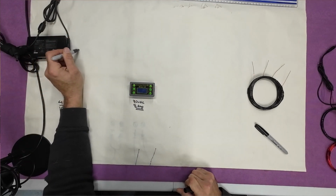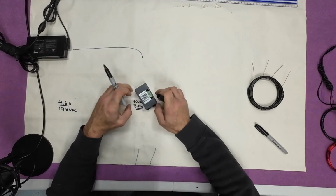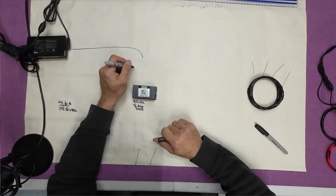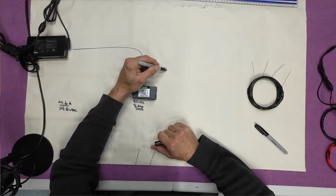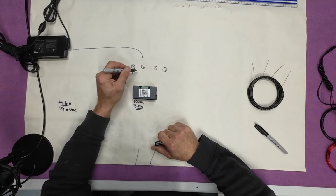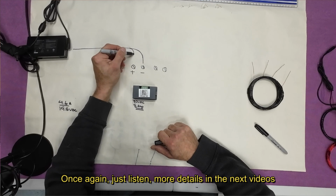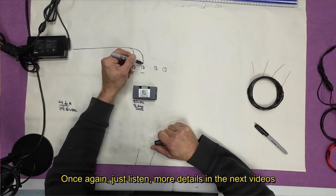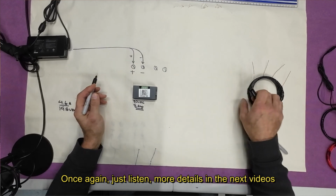So then you're going to have your wire coming in to the ZK. Now, if we turn the ZK over, you see that there's 4 screws. There's the plus and the minus. So one will go there, then one will go here. From your power supply, this will be your plus, this will be your minus, right?